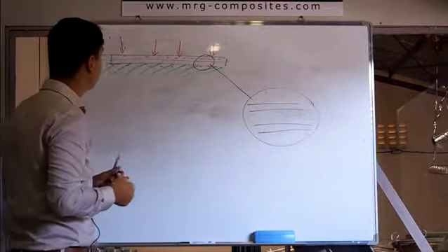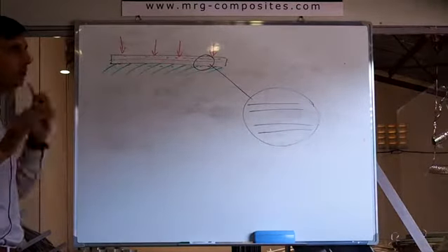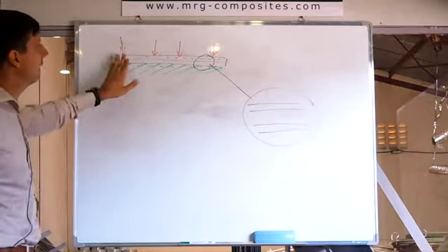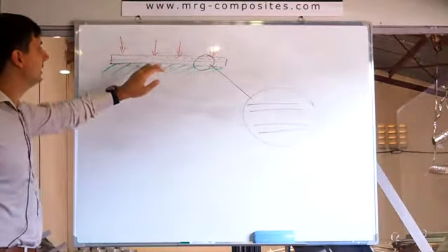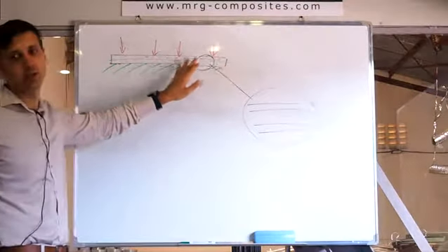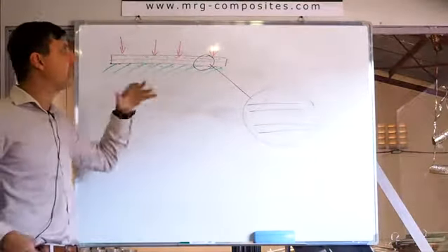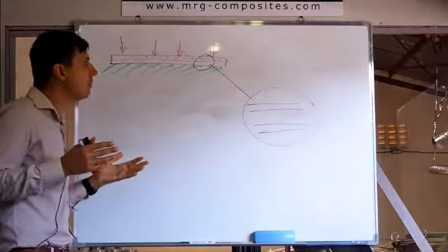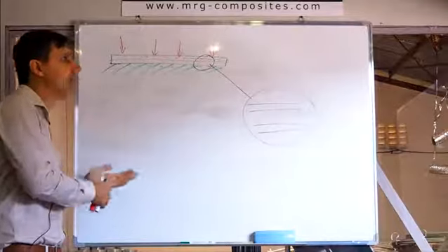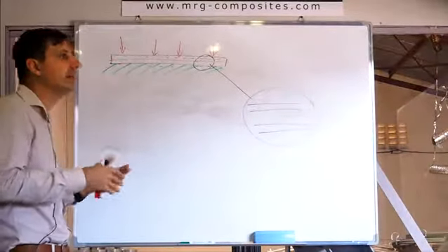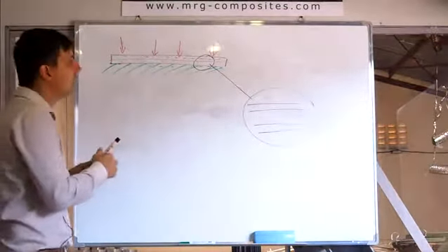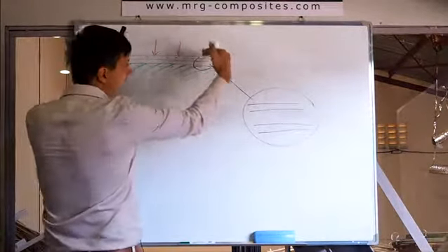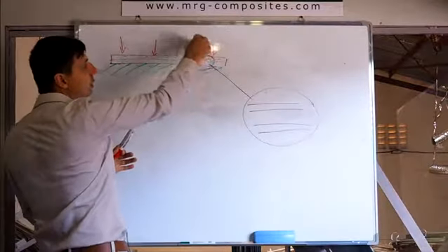We know that according to the rules, you have to calculate the beam to prevent any cracks opening anywhere. This is the rule. But in reality, cracks can appear, because of floods, maybe earthquakes, whatever. Maybe there was a flood that removed part of the soil here, but the load is still the same, so deflection here is a bit more, and it causes a crack.